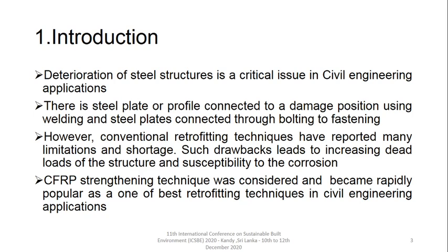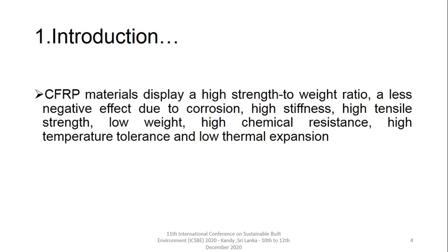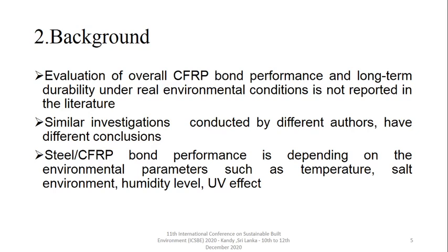CFRP strengthening technique was considered and became rapidly popular as one of the best retrofitting techniques in civil engineering applications. CFRP material displays a high strength-to-weight ratio, less negative effect due to corrosion, high stiffness, high tensile strength, low weight, high chemical resistance, high temperature tolerance and low thermal expansion.